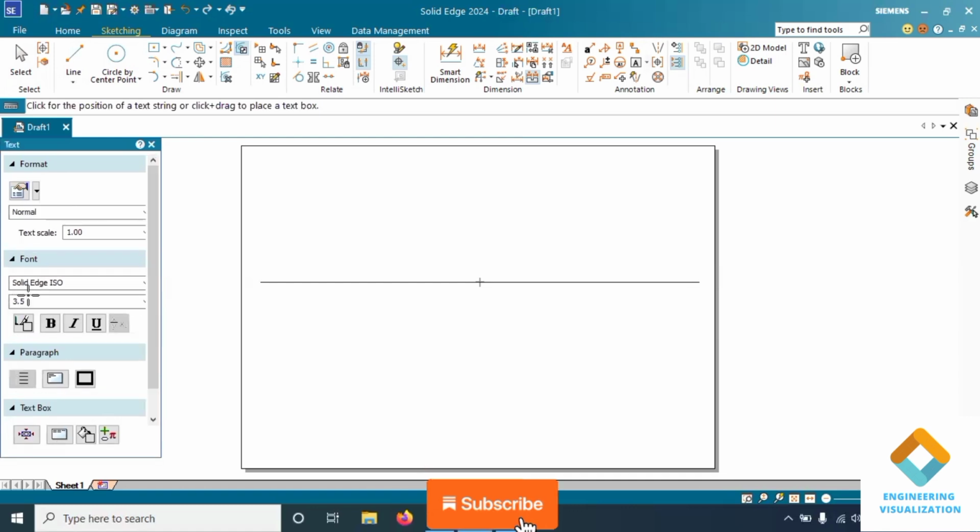First we'll draw an XY line and write VP and HP. The first position will be a circle, but for that circle they have not given any dimensions, but they have mentioned the dimensions for the ellipse, that is major axis 60 mm and minor axis 40 mm. So the major axis of the ellipse will be the same dimension as that of the circle.